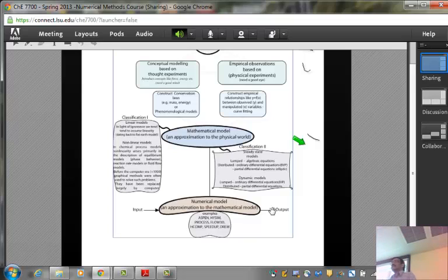It's difficult. So if it is difficult, can I take into account the spatial variation? I divide this huge reactor into small tiny reactors, and in each reactor I say the concentration is homogeneous, but it is different from the reactor next to it. And they are coupled because one is feeding into the other. If you understand that concept, that's essentially what CFD is. You have a partial differential equation, you divide that into tiny cells or grids, and you locally use the concentration rate data and allow for variations in concentrations. So you get closer to a realistic situation.